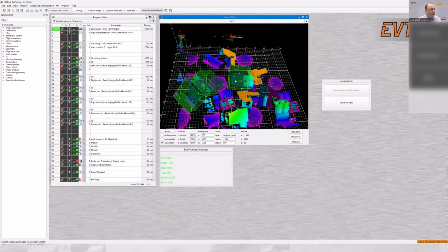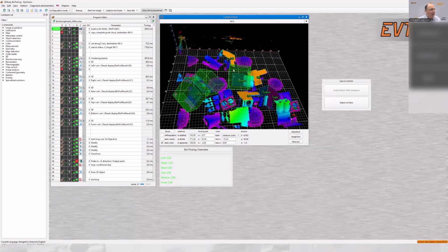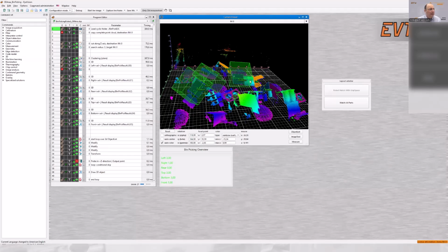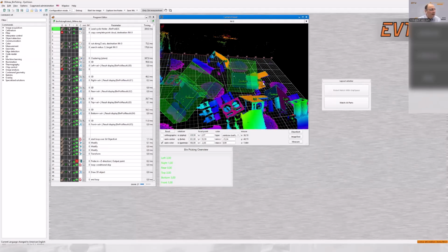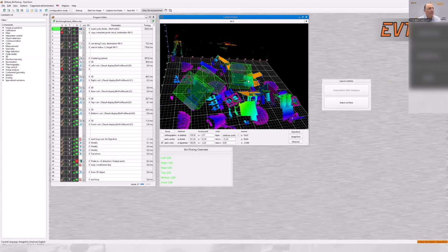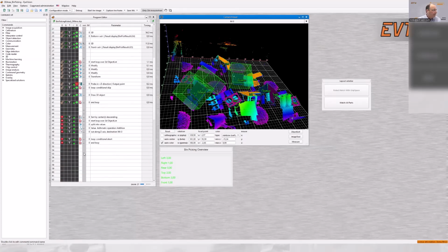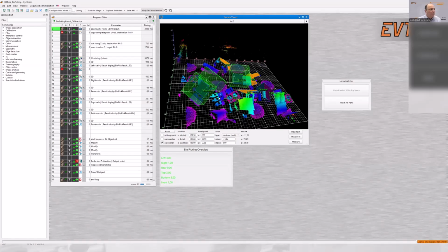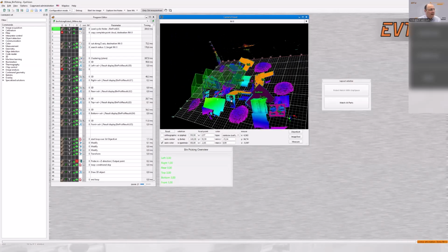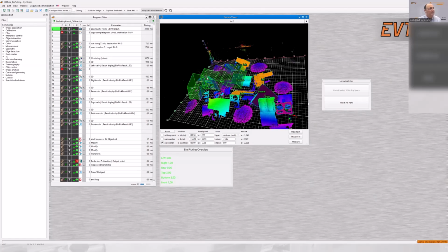And in this case, we also check the airspace above the part, if we can pick it out of the box. That's why you see these boxes. That means wherever the box is, we could grab it. And you see here, the main task is to use the 3D matcher to match the part. And after the matching, we simply check, is there enough space to grab it out of the box?